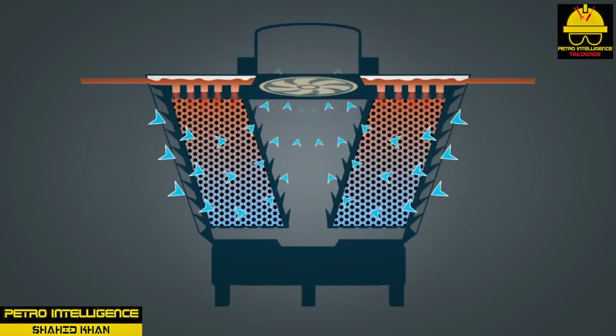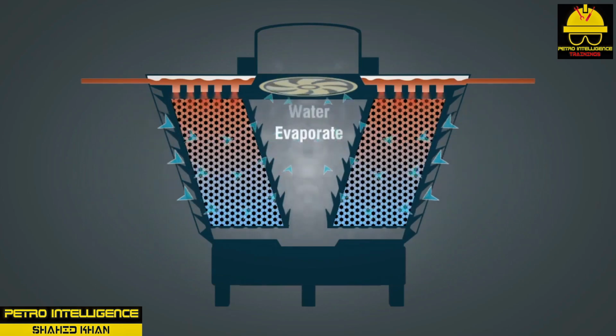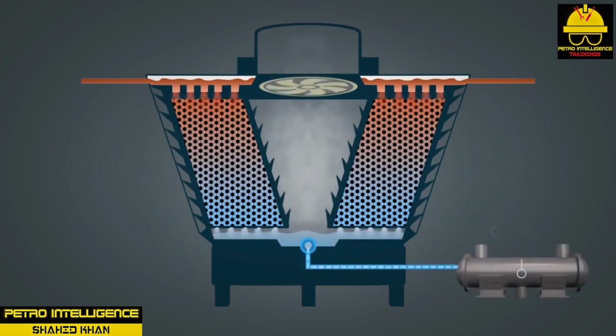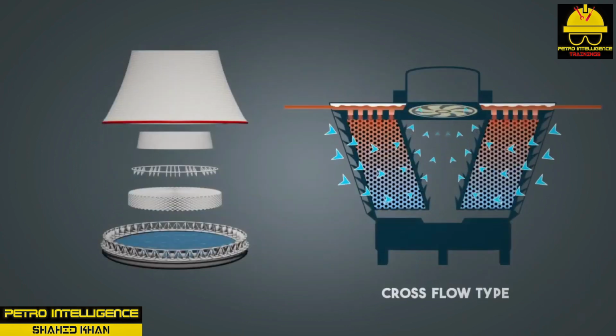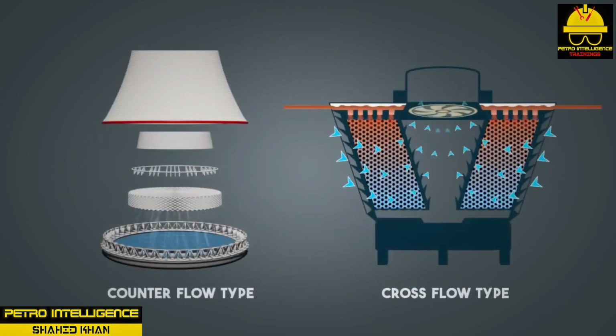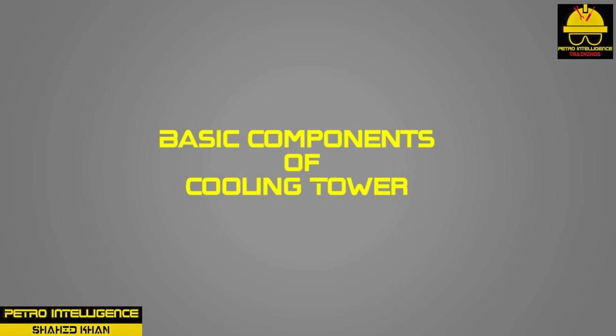The wet bulb temperature, perhaps the single most important factor in cooling tower performance, can be described in several ways. The lowest theoretical temperature to which water can be cooled in the tower. The temperature of the air saturated with water, also referred to as the dew point of air. A theoretical temperature that cannot be reached, only approached.